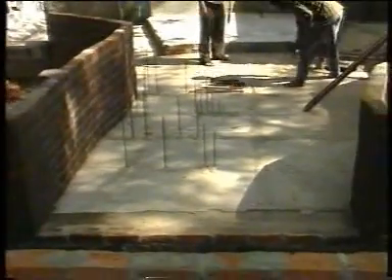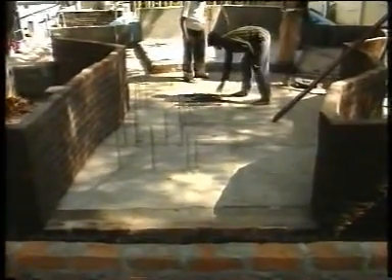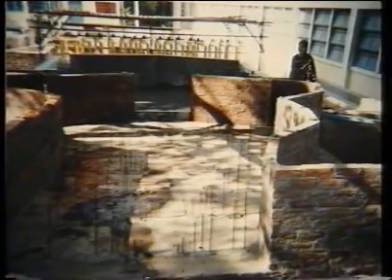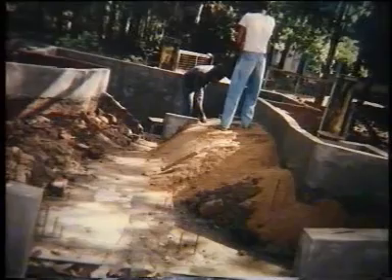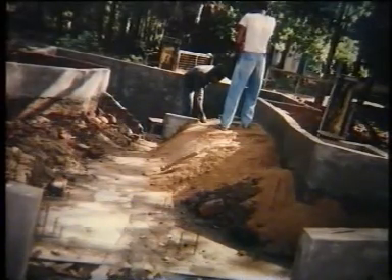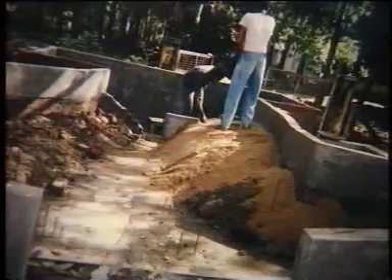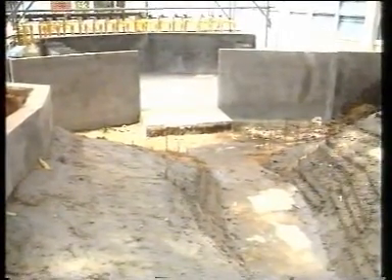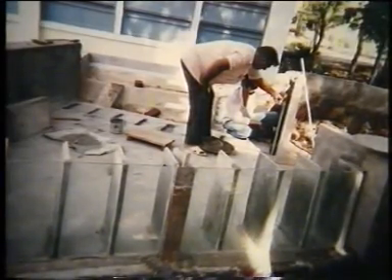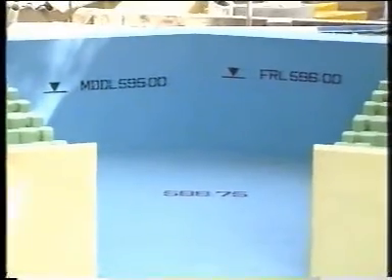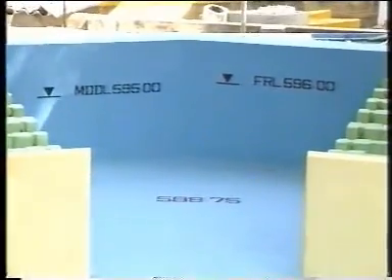Free ends of these rods represent the levels of the points on the ground. Now you can see the whole skeleton in the model. The intermediate portion is filled by sand and other material to give a shape. The top surface is plastered to facilitate the smooth finishing subsequently. This view shows the process of installation of trash rack piers. Now you can see the completely finished model.